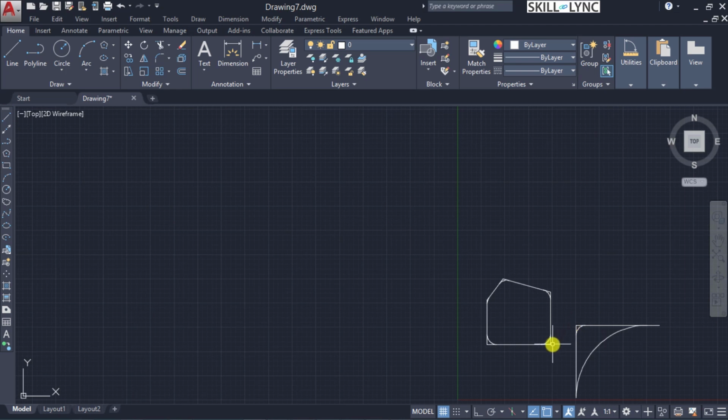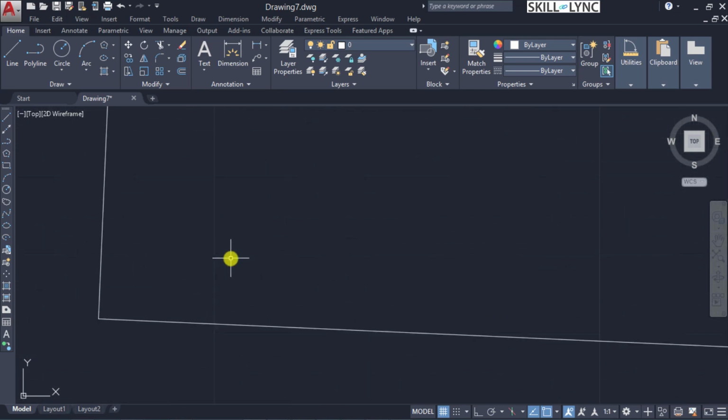And suppose we want to override a preset fillet radius in the system menu, considering that we have a smaller object here and we do not want to set the 150 mm radius on it. In that case, when selecting the object, we can hold the shift button and then select, to override the fillet that we have.